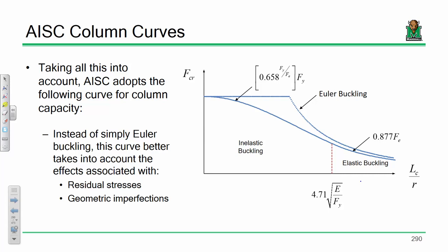So a typical plumbness limit is h/500. And so to give you kind of an idea, if you have a 12-foot column, that's about 1/4 of an inch. So think, a column that's 12 foot long, we're allowing you like 1/4 of an inch off. That's a pretty realistic expectation. So you're going to have the total station set up, right? You're going to bring the prism rod, not the leveling rod. Some people heard that, some people didn't. So you're going to have the total station and the prism rod. You're going to shoot the column and make sure that it's within tolerance. If not, you're going to use come-alongs or something like that to get it where it needs to be. So the short answer is you just have to measure it and make sure that you're within spec.